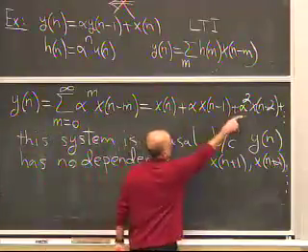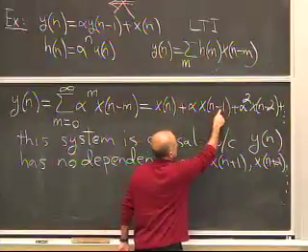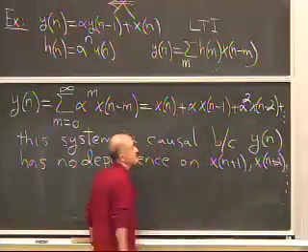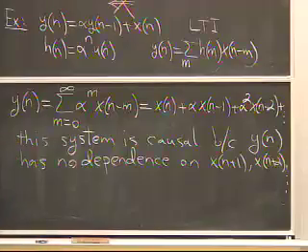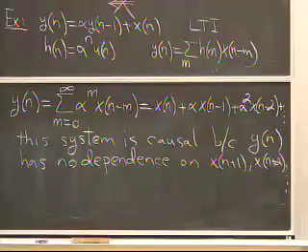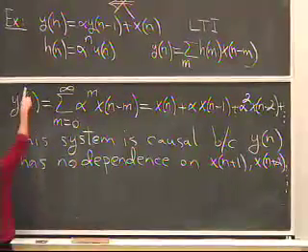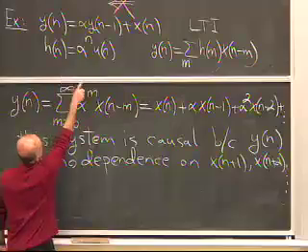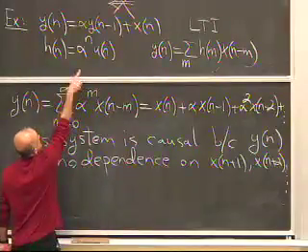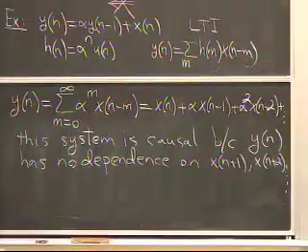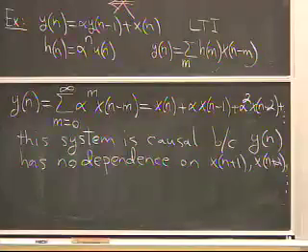But this brings out the point that the values of the input at other times play a role in the output. You can also see it if you write down a few recursions of the difference equation. But the dependence of y of n on x of n minus 1 is implicit in the previous output value. And that's why I wrote it in explicit form here.